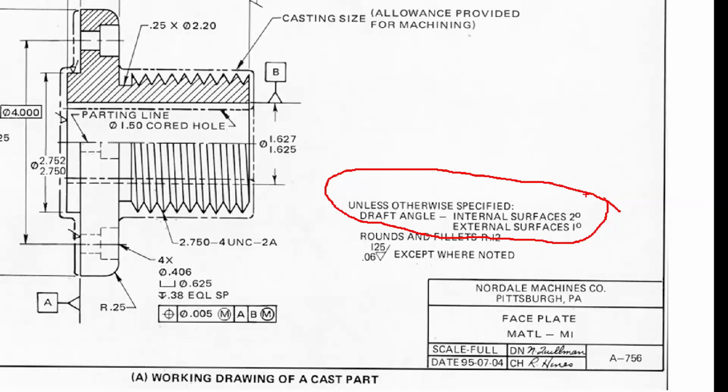And if you guys hadn't seen this little doodad back here, this is an injection molded thing, and maybe I'm getting a little bit ahead of myself, but the blue is one half of the mold, and the green's another half. Cope and drag is what they're called. They open, right? Separate open like this with a machine. This one has a special slide because it's making a hole. So parting line, right? Parting line.